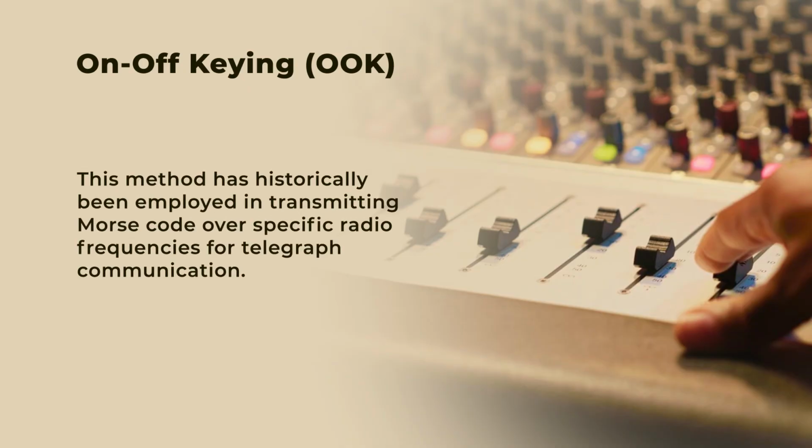This method has historically been employed in specific radio frequency applications and for telegraph communication. However, on-off keying is not particularly efficient regarding spectral usage because the carrier amplitude shifts abruptly with each change in data bit. Therefore, while on-off keying is suitable for transmitting data at low to moderate rates, more bandwidth-efficient phase modulation techniques are preferred for higher data rates.